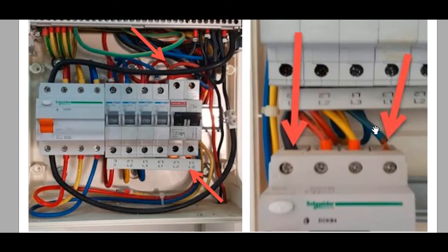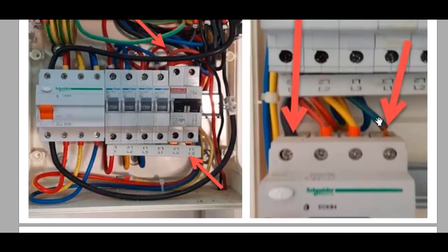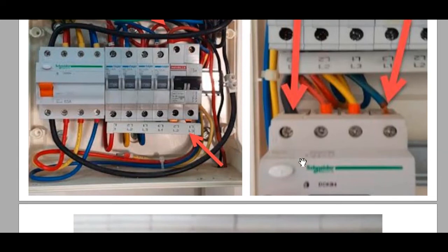As you see here, this is melting, because they don't use bootlace ferrules. Here also there is no numbering, there is no tag for the wires, and you see this phase. This is a 3-phase 4-pole earth leakage circuit breaker from Schneider. So this phase melted, and as you see here, this is melted and not tripping. Why? This is a very important reason we must discuss, because here we have a loose connection, and this circuit breaker is not compatible to use here, because they use an RCD with 300 milliamperes.